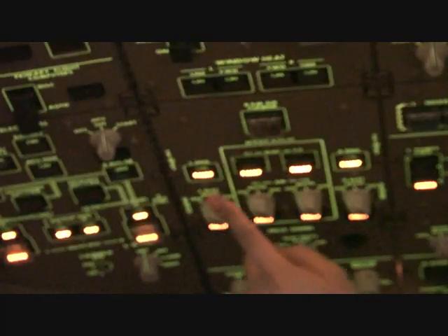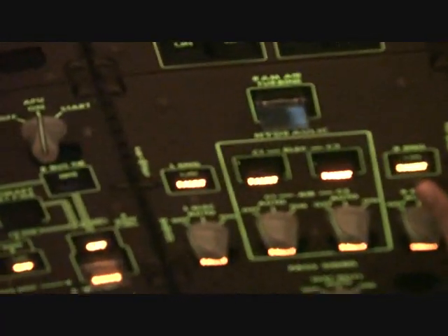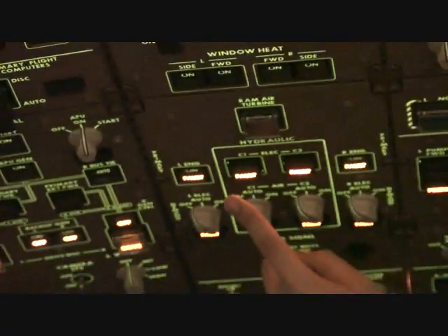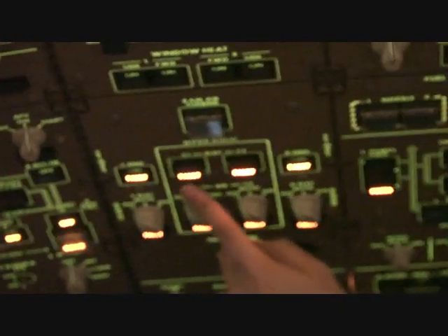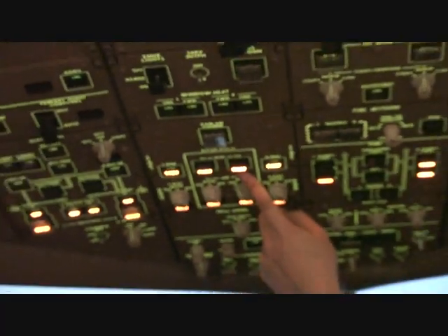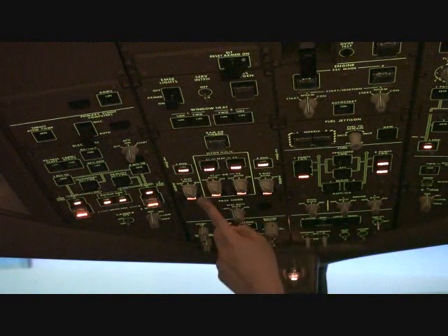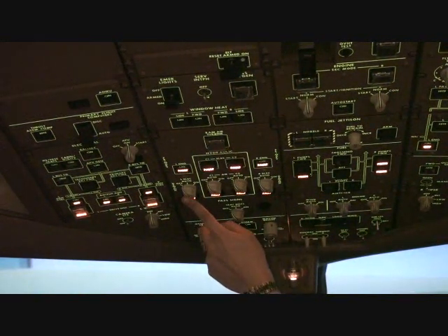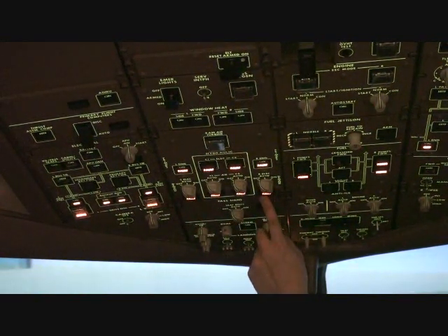Hydraulic panel set. Left and right engine primary pump switches on. Verify that the fault lights are illuminated. Center 1 and Center 2 electric primary pump switches off. Verify that the fault lights are illuminated. Demand pump selectors off. Verify that the fault lights are illuminated.